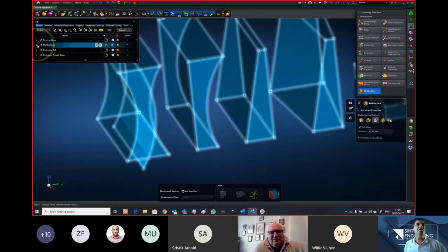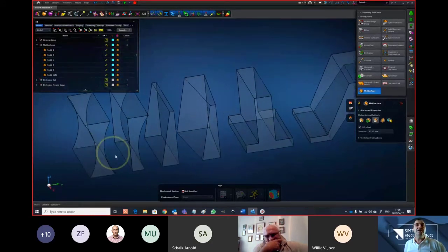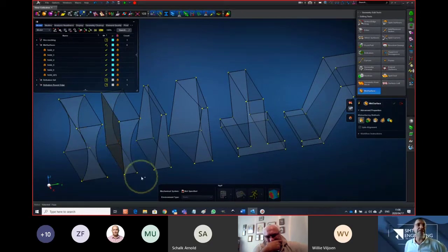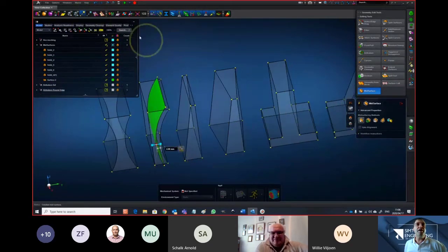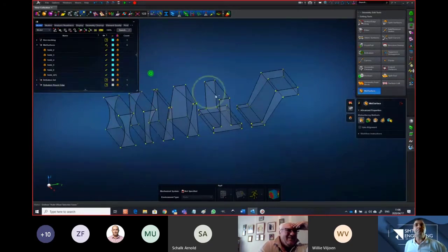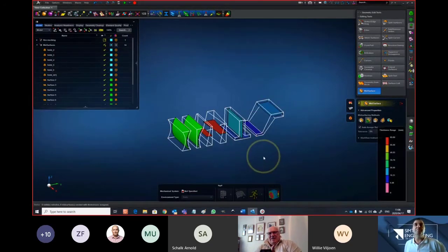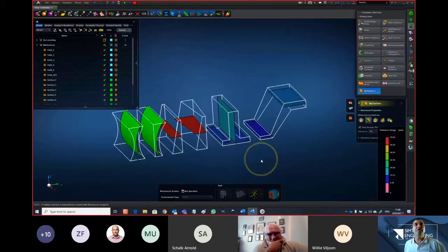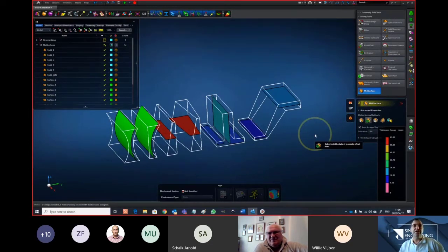Now, clearly, in a model like this, the shape and the feature was not really well suited for that. So this is where the manual method is essentially not suitable in cases like these. Or if I select that face, obviously that doesn't make sense either. The next option is the automatic option that I would use predominantly most of the time on geometries, but you can also see that in many cases it fails or doesn't really produce the result that you were after. The reason for that is that the auto mid-surface option, the second one, is actually more suitable for constant thickness solids.